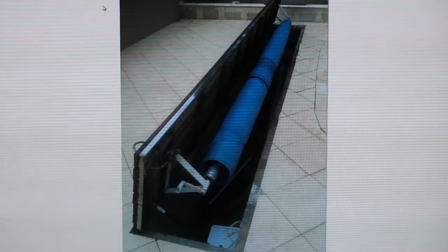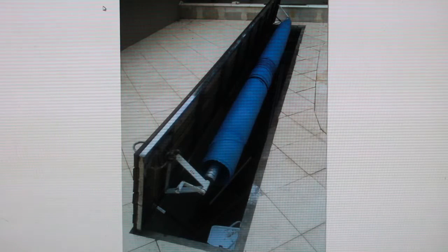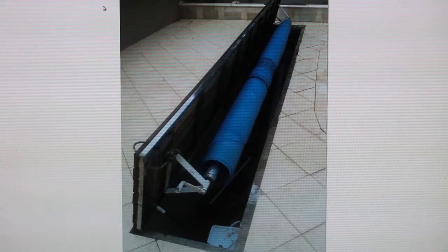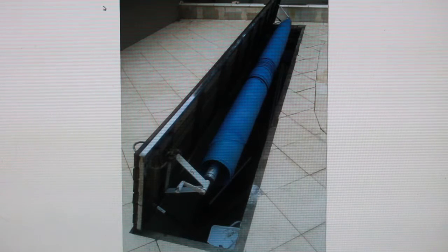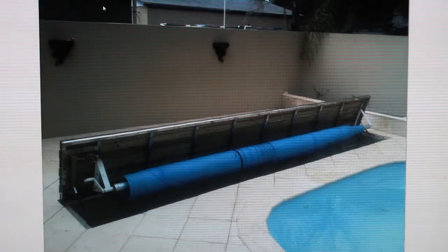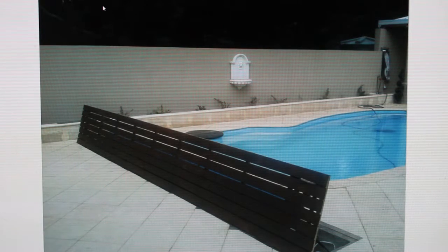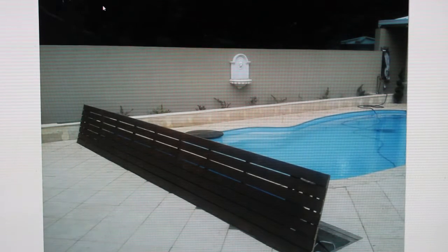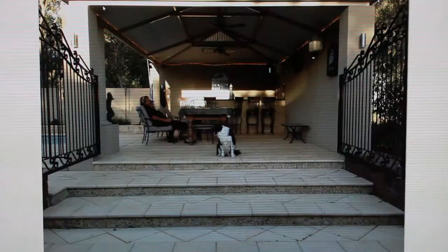Even the pool cover, I designed a below ground cover system. That lid's about 300 kilograms, with 250 Newton metre gas struts to lift that lid up. So that was pretty huge. All jackhammered out, decked. And a 3x6 stainless steel frame, by the way, because it's a saltwater pool. So that was a bit of a challenge design to put in, but it works really well.